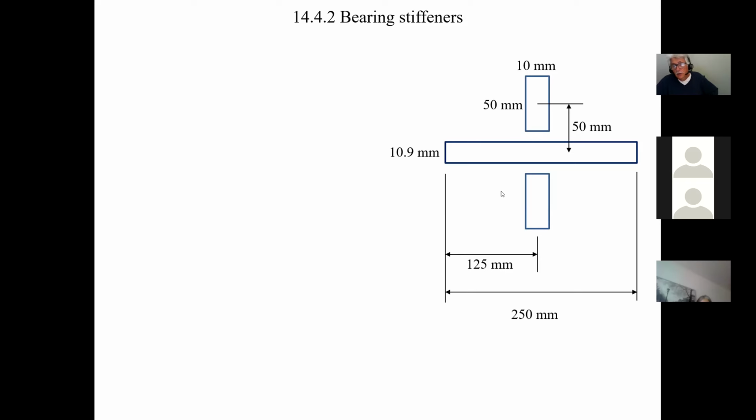And now of course, what I need to do is calculate the weaker axis. So Ix is equal to IC, and this is where all that good stuff comes back into practice, your parallel axis theorem, where you're going to transform this and calculate your Ix value for this particular cross section. And you know that the Rx value is equal to Ix over A, so I calculate the area of this, okay? If you need to do it, you calculate the area of this. So that gives you the Rx value, because you know, in terms of Y, this is much stronger because of this height here. So therefore, this is the one that's going to govern. But if you're not sure, you should do both.